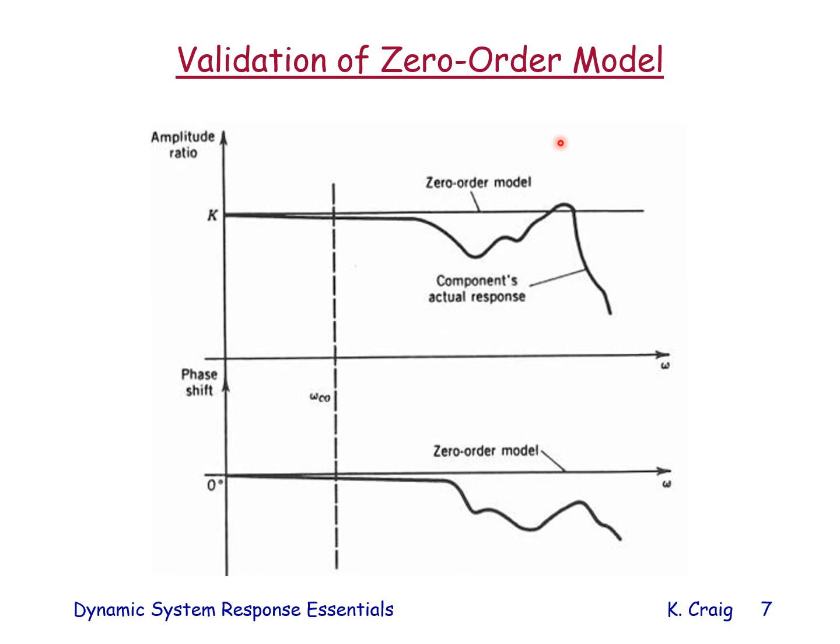If you have a very high order model, but over some frequency range of interest, some frequency range of operation, for example, in this low frequency range below what we call omega cutoff, the system behaves like a zero order system. Amplitude ratio constant, independent of frequency, phase angle 0 degrees, independent of frequency. Then over this range, a zero order model is most appropriate. It perfectly fits. To do anything more complicated, if all you're interested in is this range of operation, would be foolish. It'd be needless complexity.